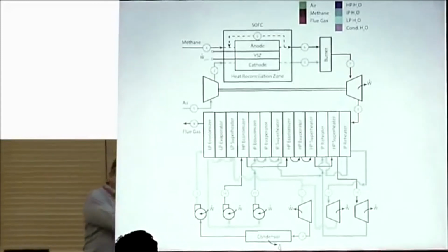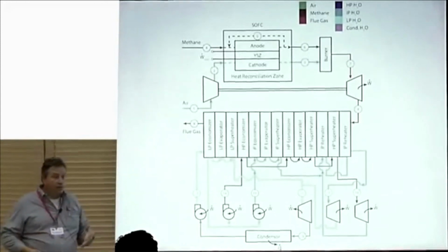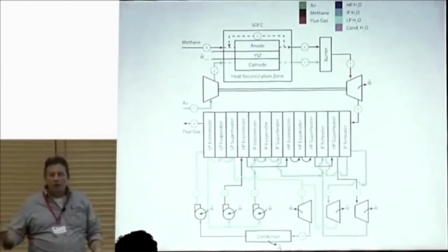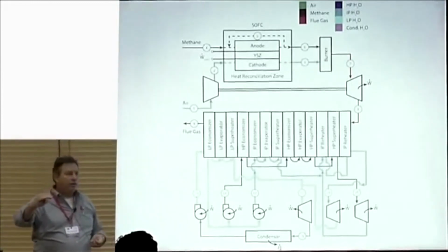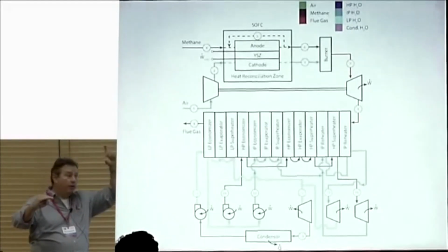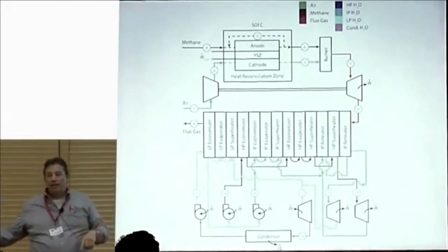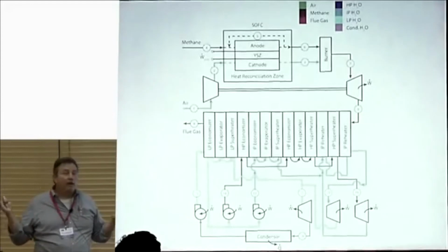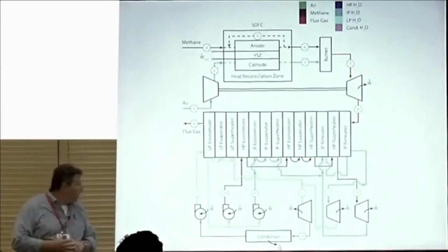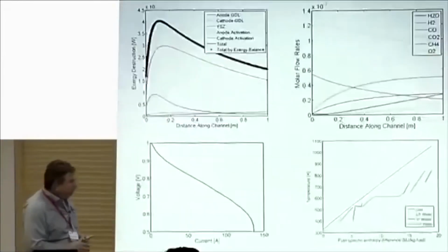So given that the previous example on low heat rejection engines, playing out turbines and overexpansion and thermal barrier coatings and all this stuff, we're capped at 60. I mean, to me, that was the big message. I can't get past 60 for that system. And I got that big old bin of combustion irreversibility sitting up at the top. It makes me go to the other side and say, well, I got to be more reversible. I got to restrain the reaction. Let's go look at the system with a restrained reaction. So that's what Rebecca did.